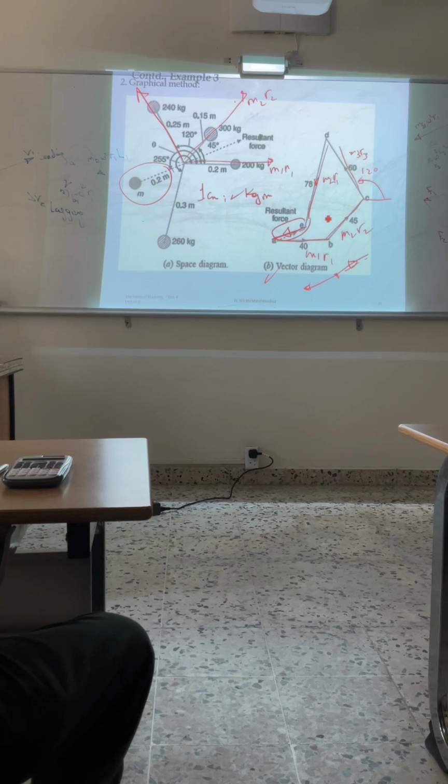Once you reach this one, you are claiming that your balancing mass is taking everything to 0. So here you go, this is my MB, RB. Clear? You take that length, multiply it by the scale, and make it equal to 0.2 m. Remember when we gave our balance equal to 0.2? Yes. Then you are able to find the mass.